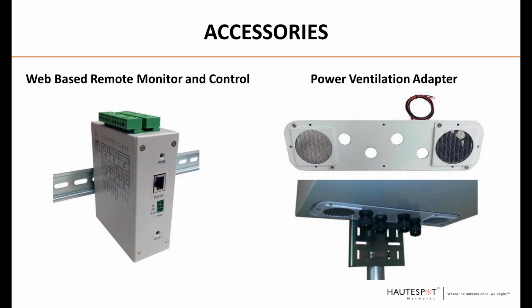In very hot climates, it's a good idea to add the power ventilation adapter, and it usually kicks on at about 122 degrees Fahrenheit, and will generally cool the system in about 5 minutes, which is going to give your batteries longer life and more battery capacity.